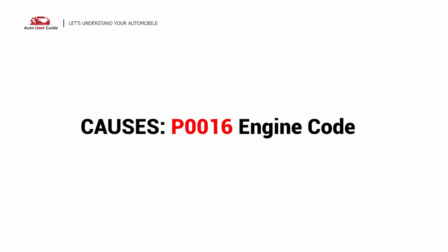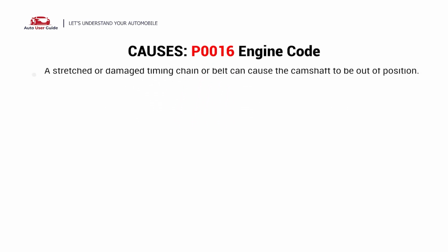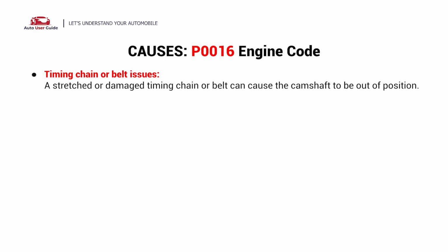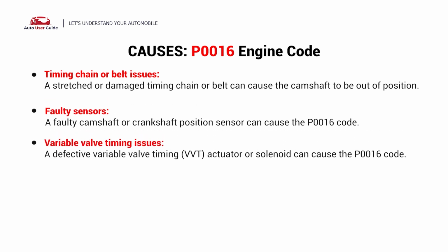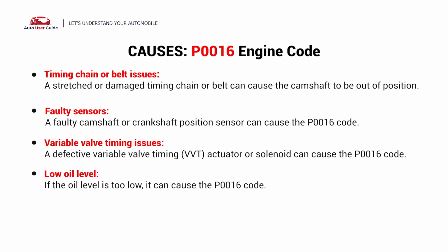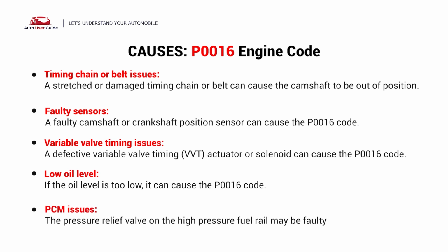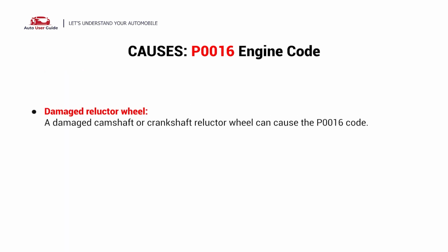So what causes this imbalance? Here are the most common culprits. This error could be caused by these possible faults in your car. Timing chain or belt issues. Faulty sensors. Variable valve timing issues. Low oil level. PCM issues. Damaged reluctor wheel. Worn guides.